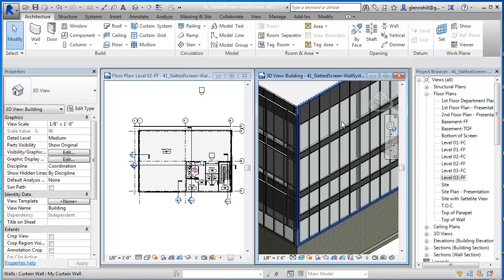So we're going to put a slatted screen on this west wall here, and it's going to be made out of some kind of approximately 2 inches by 4 inches, 2 inches wide. We'll just say 2x4s right now, and we'll build it like it's being done with wood. And the first thing we want to do is build our frame.